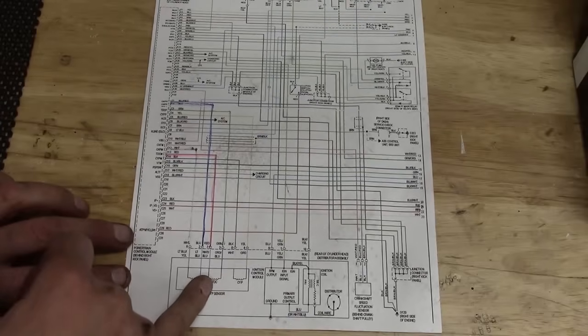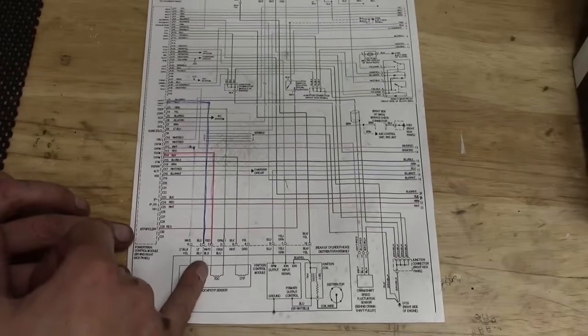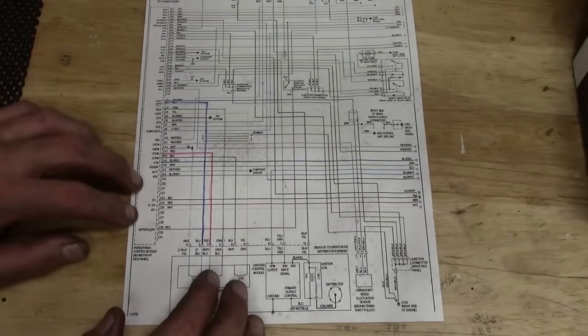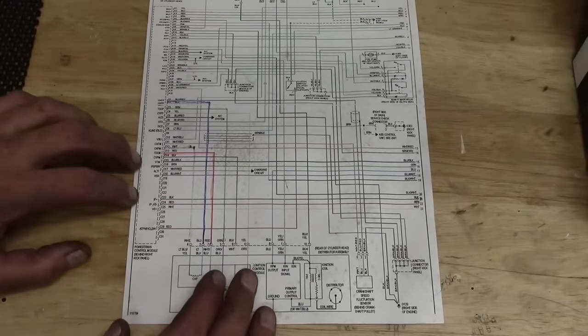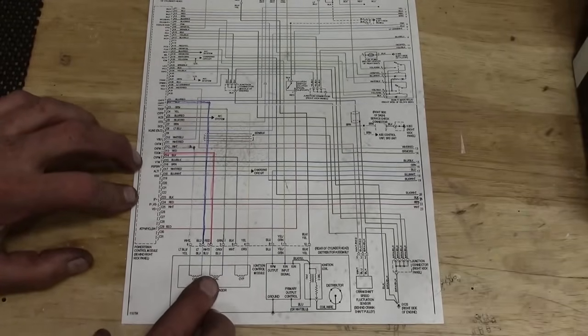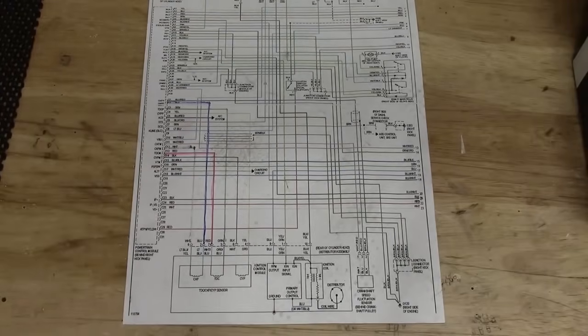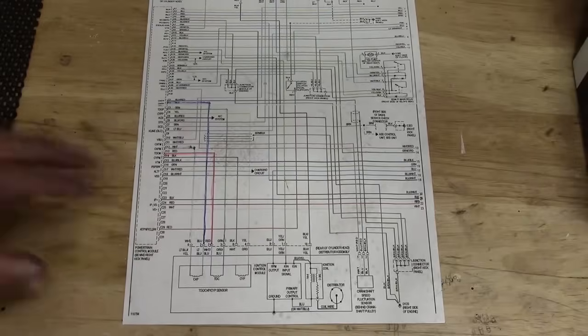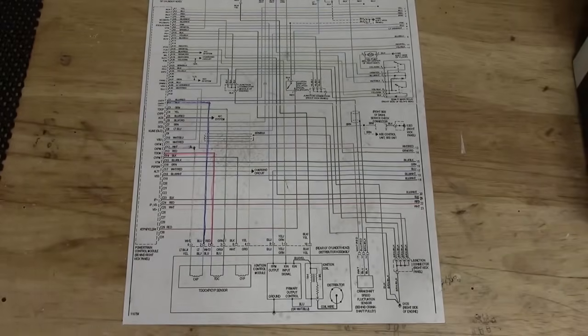But again, we can see this is definitely going to be a similar design as our CKP here. It's going to be an inductive 2-wire sensor. It's going to generate voltage that we will be able to pick up if we need to test that. And then this third one, I really have no idea because I can guess what CKP and TDC are. CYP, I honestly can't even fathom a guess. Camshaft, yaw position, hell, I have no idea what that is.